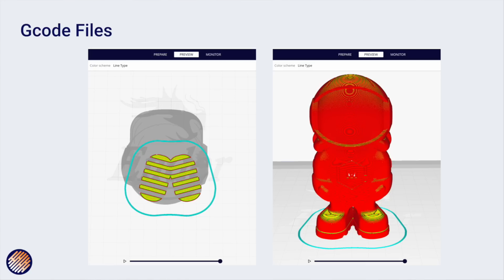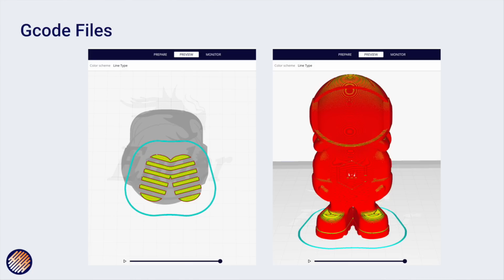So it's going to create one of these segments. And so each one of these changes of direction is a G-code command. That's all G-code is. And if we look at it in a slicer, we can see here on the left-hand side what a single layer looks like. And you can imagine how the G-code would be written to create that layer. And by stacking those layers one on top of the other, you end up with a shape like the shape you see on the right-hand side.